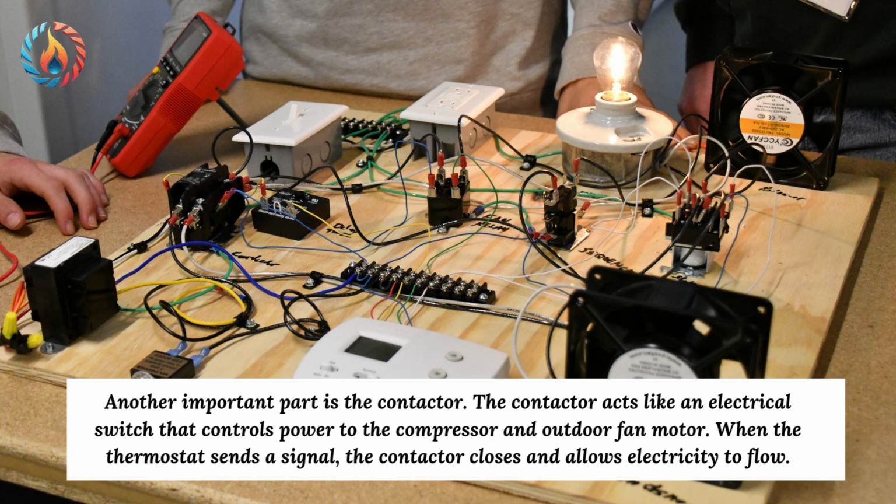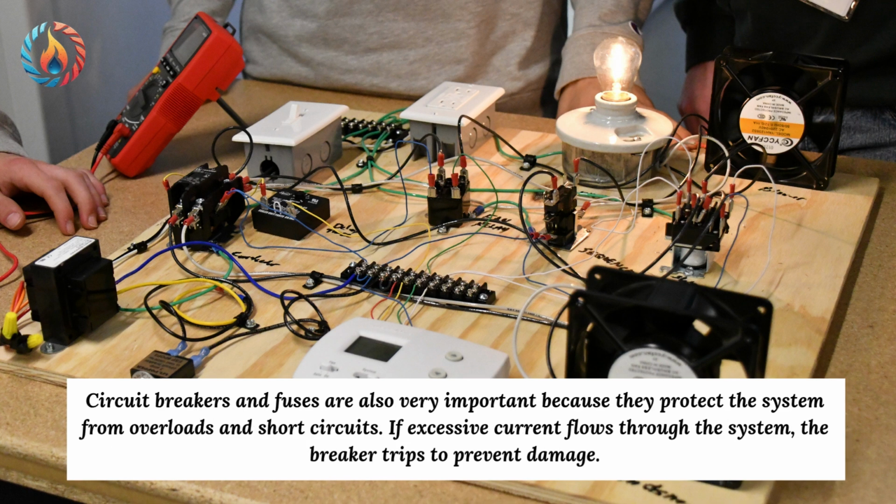Another important part is the contactor. The contactor acts like an electrical switch that controls power to the compressor and outdoor fan motor. When the thermostat sends a signal, the contactor closes and allows electricity to flow. Circuit breakers and fuses are also very important because they protect the system from overloads and short circuits. If excessive current flows through the system, the breaker trips to prevent damage.